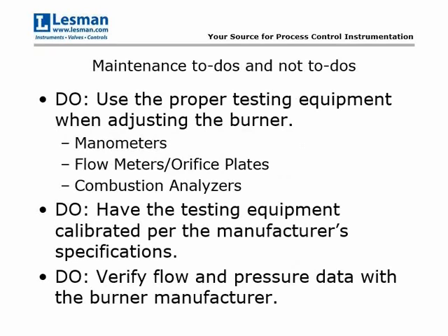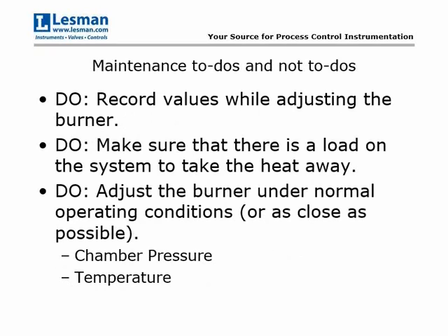Again, each burner is different. The manufacturer of the burner has cut sheets and data for the operating conditions for that burner, so flow and pressure for that burner, as well as a range of excess air that that burner should be set up for. So if you're going to go through and get into one of these applications, you'll definitely want to make sure that you get a hold of the burner manufacturer and make sure you have the most up-to-date and current literature so that you know what flows and pressures you need to achieve.